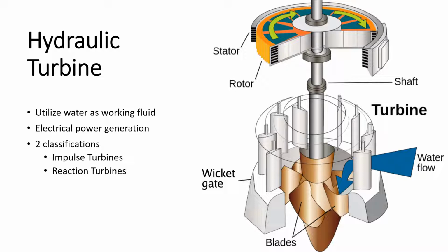Impulse turbines generate the force needed to move the blades solely by turning the fluid without a pressure drop in the blade passage. They also operate most efficiently with lower flow rates. The dentist drills mentioned earlier in this presentation are typically of the impulse class. Reaction turbines, however, generate forces with a combination of fluid turning and the force resulting from the acceleration of the fluid relative to the blades. They operate most efficiently with high flow rates, which is why wind power mills are typically of the impulse class.